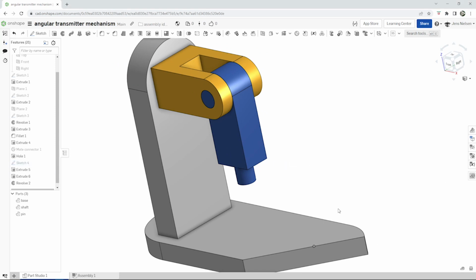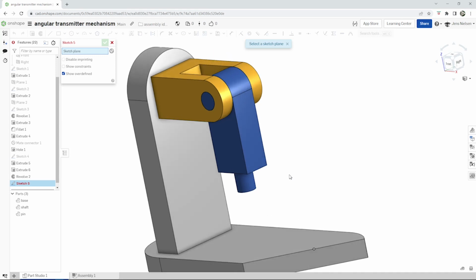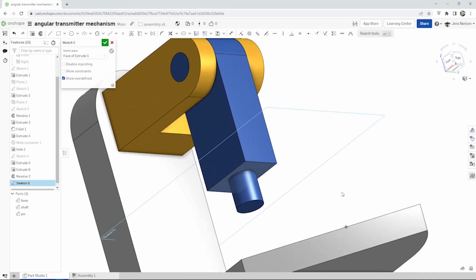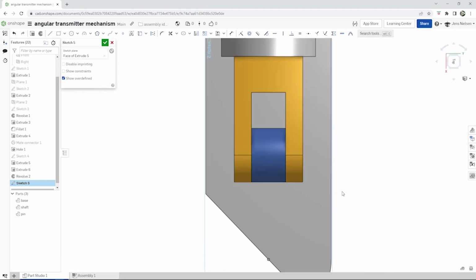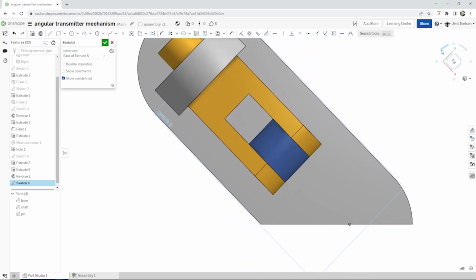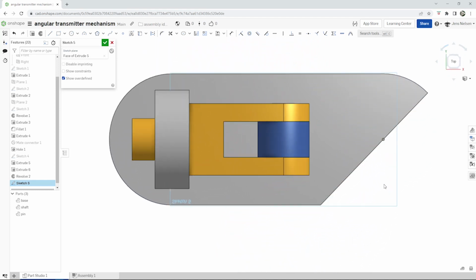Now let's model that link. I press S from my sketch tool, pick that plane, say N, turn that around, and start with a line from here, going down, connect that to that edge, give that right angle,